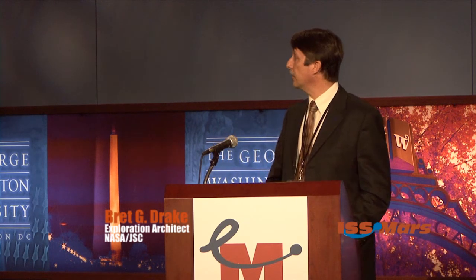But that's also large volume. Being able to launch large volumes is also key. I talked about entry, descent, and landing. Today, our capability is limited to about 1 metric ton of landed payload on Mars. To do this type of approach, we're going to have to get to at least 20 tons. Our preferred approach is to get to about 40 tons of landed mass, or usable mass, on the surface of Mars. So entry, descent, and landing, new technologies and new techniques to serve that is really critical.